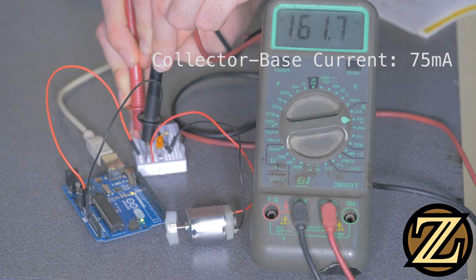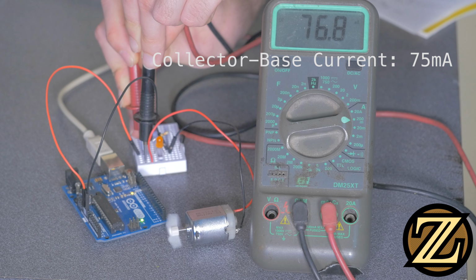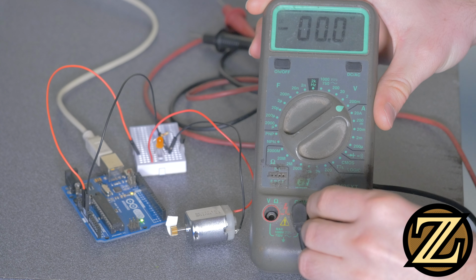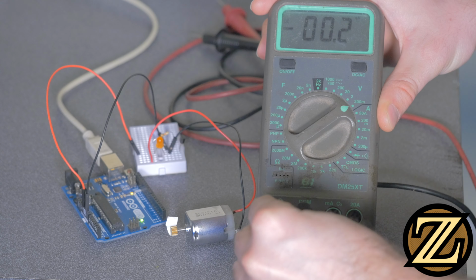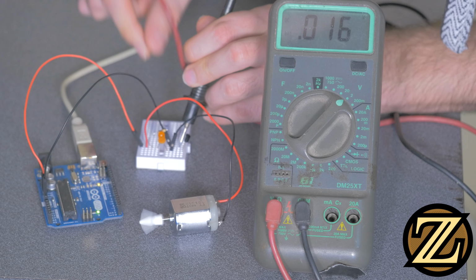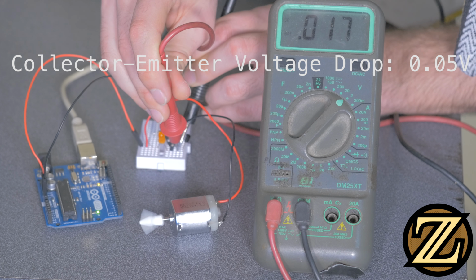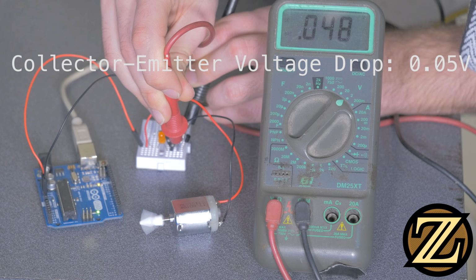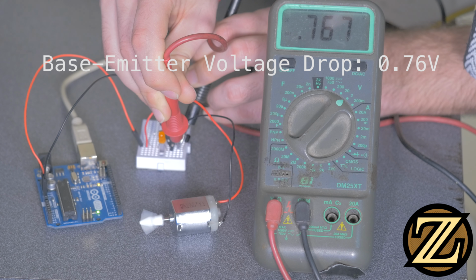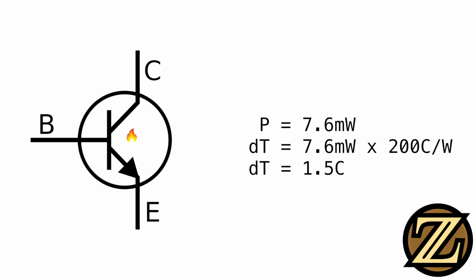When I hook the example circuit up and take measurements, I see that indeed we do get about 75 milliamps current draw from the motor. When I switch to measuring voltages, we see that we get a voltage drop across the collector and emitter of 0.05 volts, which is less than the 0.3 volts maximum the datasheet specified. Across the base emitter, we get a voltage drop of 0.76 volts, and this is within the expected 0.6 to 1.2 volt drop the datasheet indicated. This means our transistor is dissipating approximately 7.6 milliwatts, which should equate to a temperature increase of 1.5 degrees Celsius.